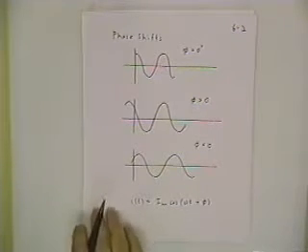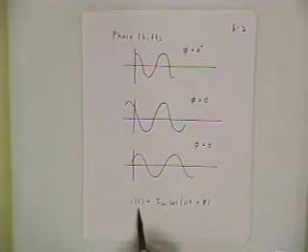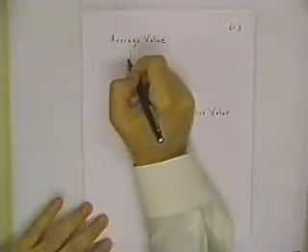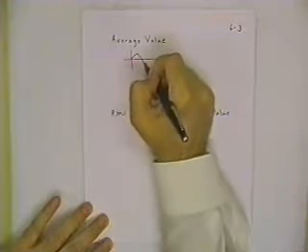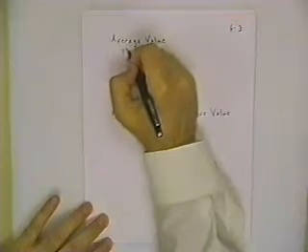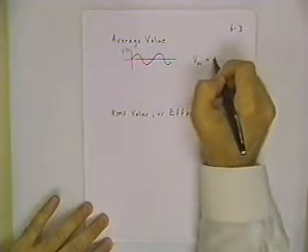So I hope that helps you in sorting out problems involving actual values for phase angle here. There's an even better way of resolving that with a notation called phasors, which we'll get to in just a few minutes. Before I talk about phasors, though, there are a couple more basic calculational items to know about AC waveforms. One is the average value. If you have, say, a typical sine wave oscillating about 0, and this is V of t, V average for this waveform is equal to 0.